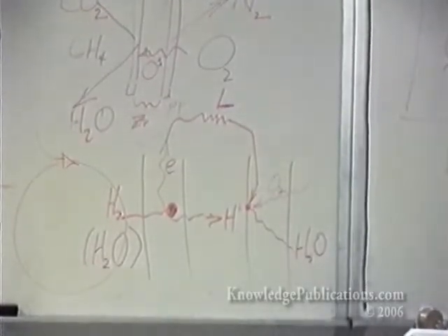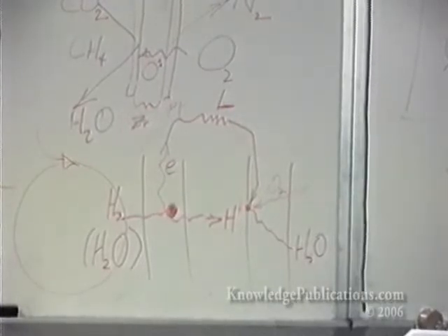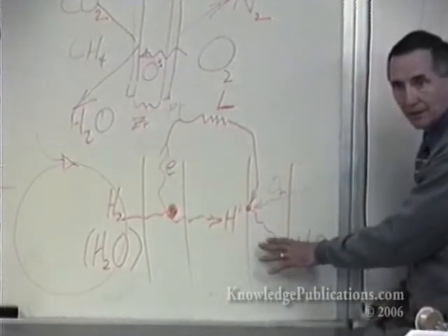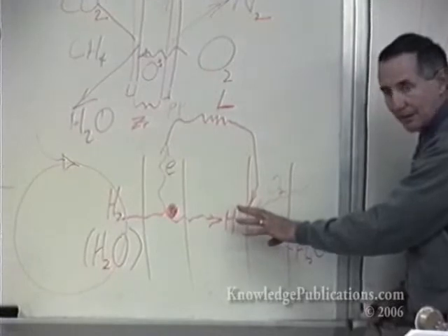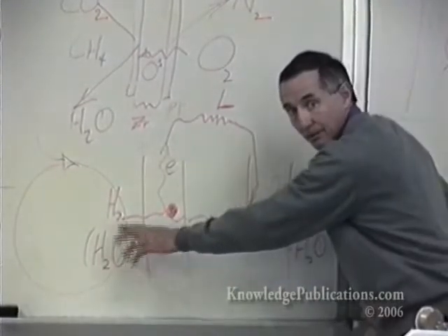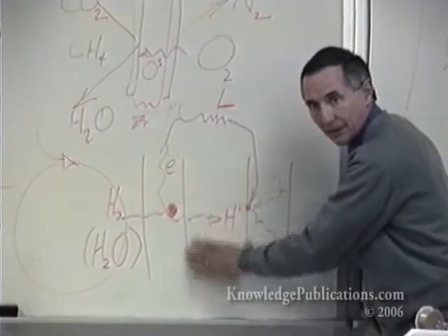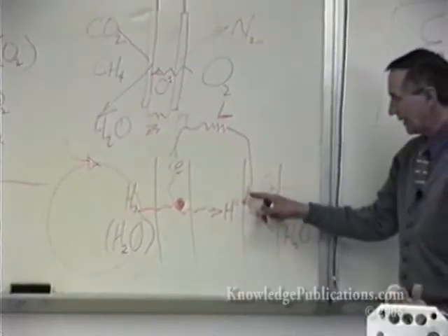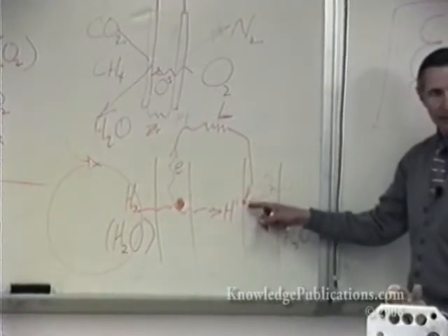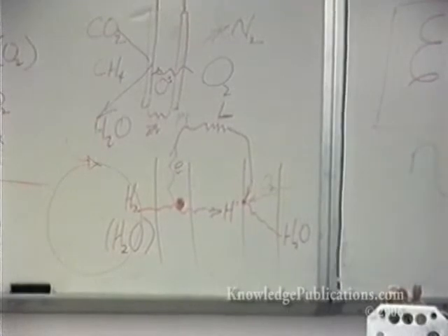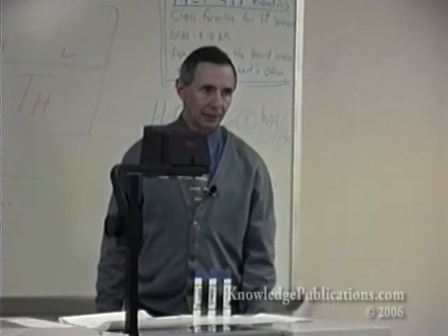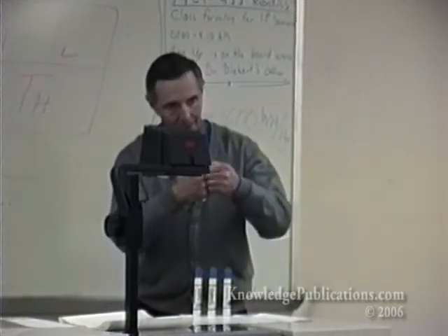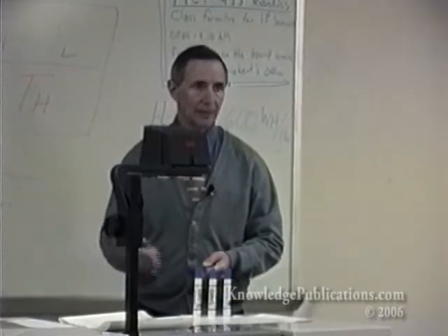That is an excellent arrangement, but it illustrates the concentration problem of buildup of the product, the water, and blocking the reactants, one or both. So you have this balance going on. You have water removal, water addition to maintain the integrity of the membrane, and you must maintain the integrity of the catalysts. These are typically platinum catalysts with no contamination, no buildup of carbonates or oil or anything out of the fuel supply that would blind them or chemically combine them so they couldn't react further in serving you as a catalyst.